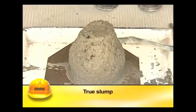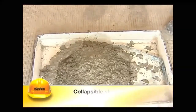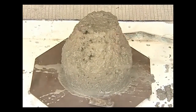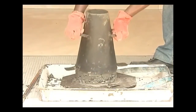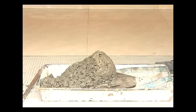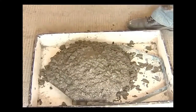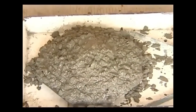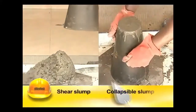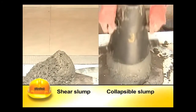The slump may either be a true slump, a shear slump, or a collapsible slump. The true slump is the desired form of slump that we require. In harsh mixes, the concrete slides down in an inclined plane. This is known as shear slump. In collapse slump, the concrete collapses as soon as the cone is removed. It usually occurs in very wet mixes. The concrete demonstrating a shear or collapse slump is considered unsatisfactory.